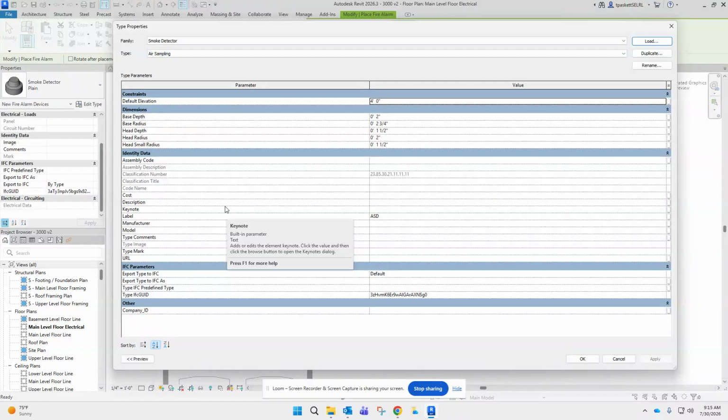Now, I want you to pay attention. I am not saying CO2. We don't check for CO2 in a house. That's what you breathe out, and that alarm would never turn off. That's what comes out of your lungs is CO2. CO is what's a result of combustion, and that's what causes people to die. Okay, so we don't want that to happen.